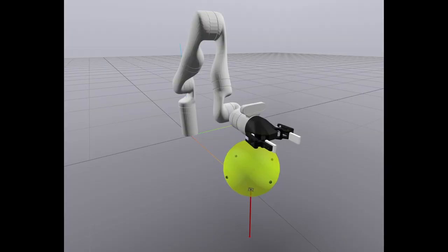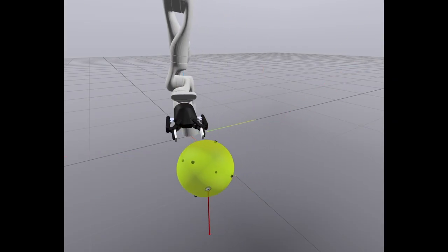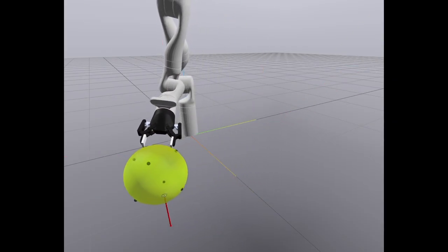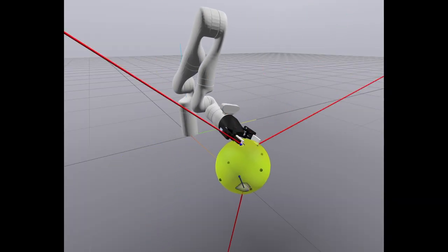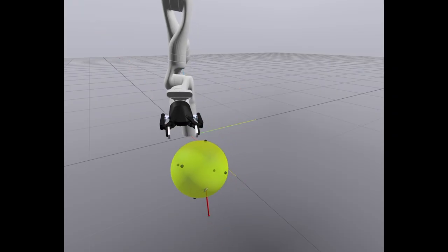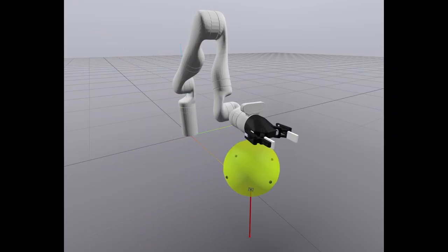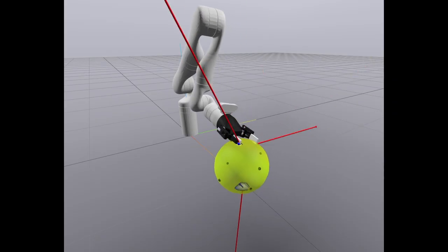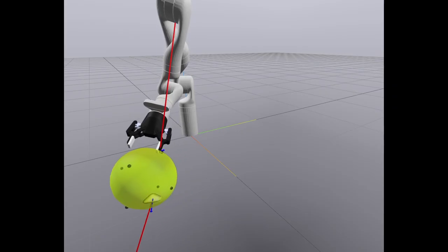We demonstrate end-to-end differentiation through contact using an out-of-the-box implementation of contact-implicit iLQR using Drake. In our example, a Kinova Gen 3 robot arm efficiently plans a trajectory to move a ball to a target position on a plane without predefining the contact sequence. Our hybrid approach uses automatic differentiation through the geometry engine and propagates gradients analytically to reuse factorizations from contact resolution.